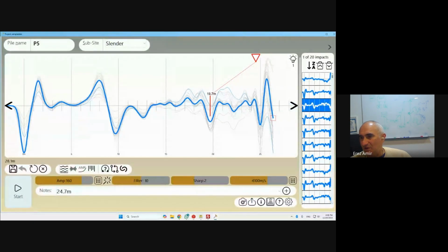Again, look here. In this case, this pile definitely has a huge bulge in this area. Remember, it's going first up, then down. So it's a local bulge. And after that, this might be the second reflection. Who knows? So really trying to analyze these piles is very risky because you're just going to write nonsense.